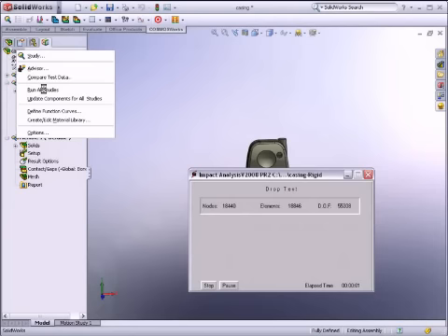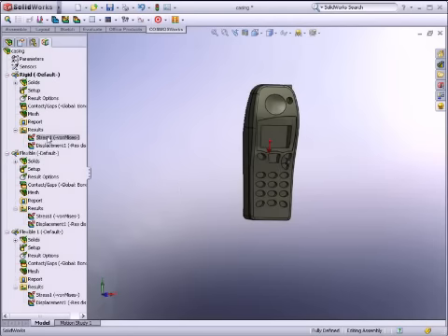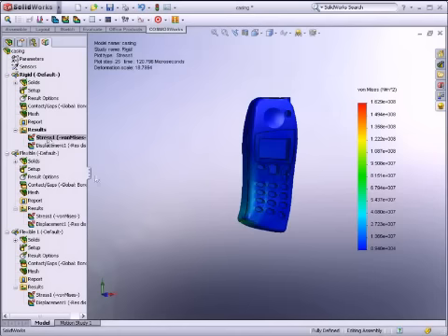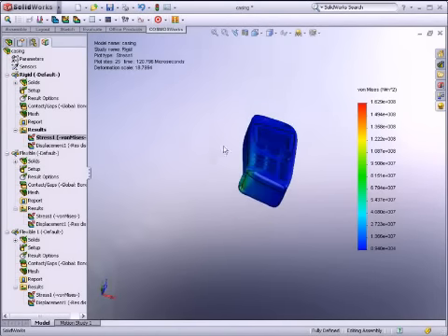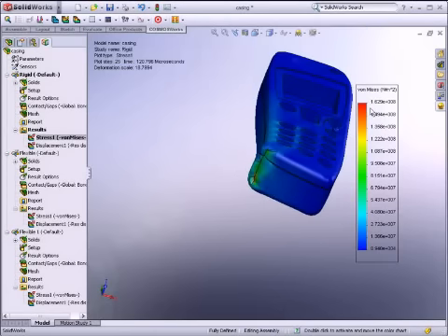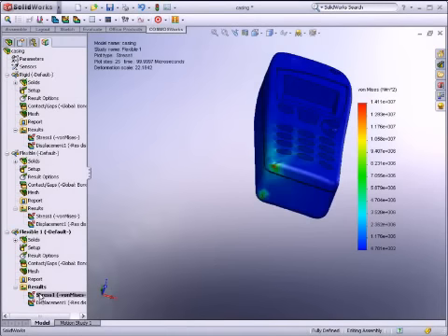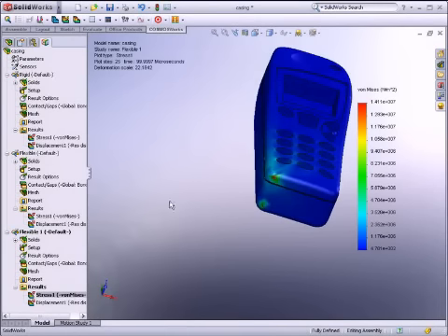Now, let's run all three analysis studies using the batch run option. We will fast forward through the process and review the results. First, let's have a look at the rigid results. You can view contour plots of stress, displacement, and strains at the exact time that the program stored the results at all locations of vertices and reference points after the impact.